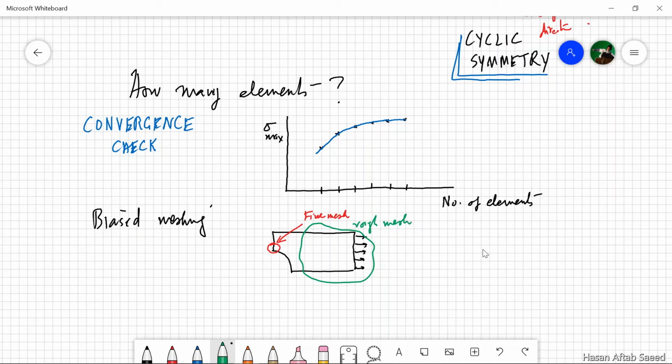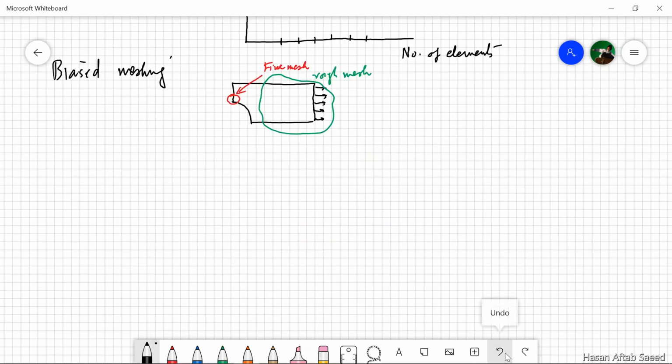Now the problem is, going from fine to rough, sometimes there's a drastic change in the size of the element and/or a drastic change in the shape of the element. Whenever this sort of distortion takes place, there are many quantitative measures of gauging these distortions, which will result in ill conditioning. Aspect ratio we just discussed when we were talking about plane stress and plane strain simplification.